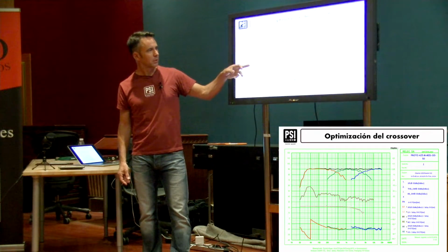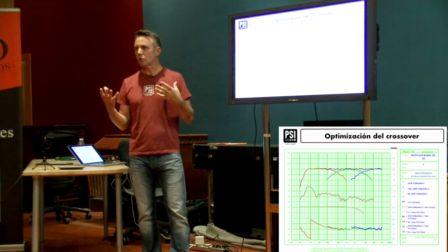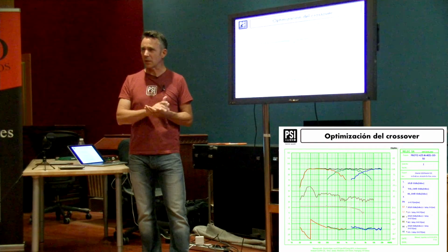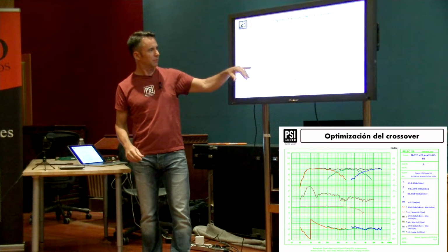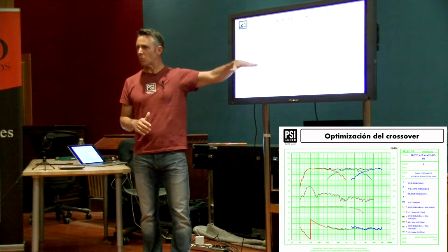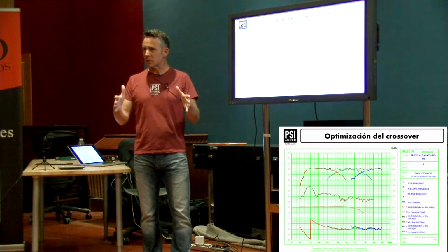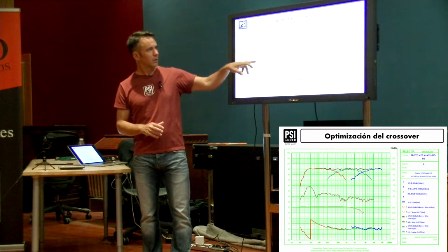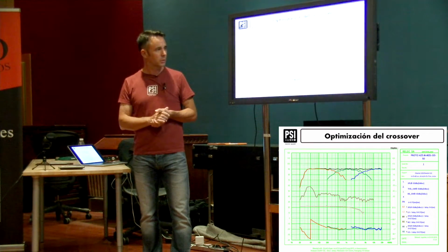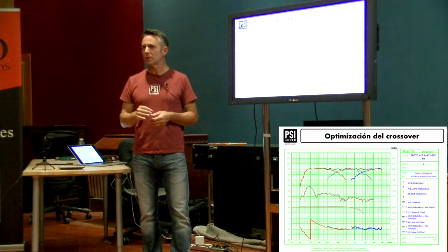This is the distortion. So you have harmonic distortion and then non-harmonic distortion. Harmonic distortion is not too much of a problem because it's harmonics of the signal itself. It sounds quite natural, but it still has to be very low, and normally in the range of 50 dB underneath, or under 1% of the sound is harmonic distortion, and that's the mechanical little vibrations in the box itself. But it has to be low, and in low frequencies there's a lot of energy, so there's more distortion in the lower frequencies.